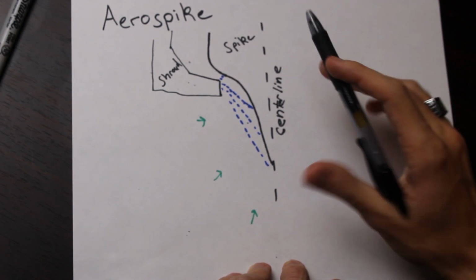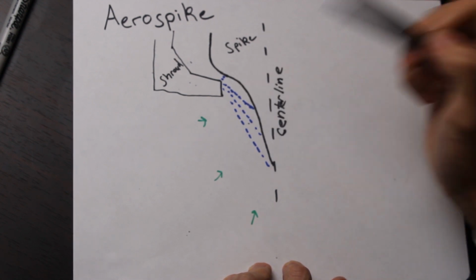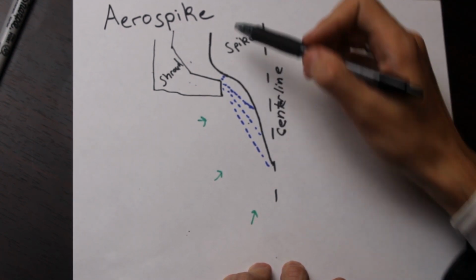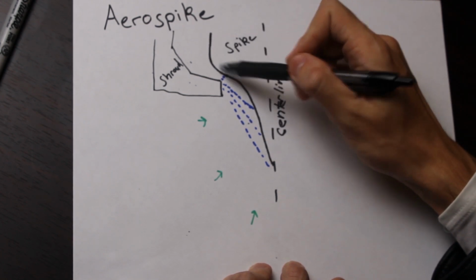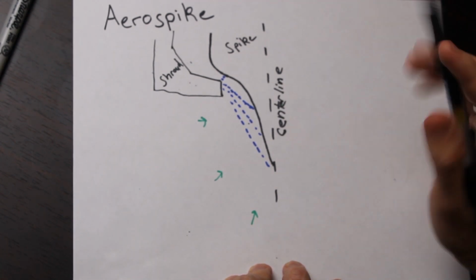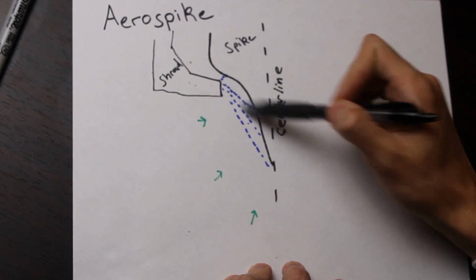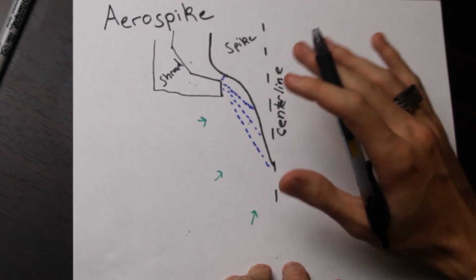So our plan here is we're going to draw in a lot of these Mach lines. We're going to find out where they hit the spike using some trigonometry, and then if we draw in enough of those and we get enough points, we'll be able to tell what the entire profile of the spike is just by connecting the dots to find the final spike profile. So now I've left the hard question for last, and the hard question is, of course, how long are these Mach lines and where do they hit the spike? And this is where all the math happens.